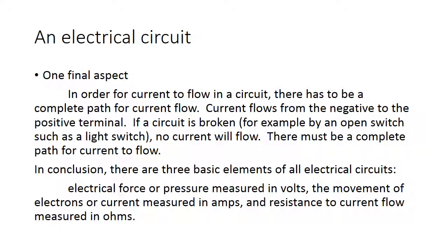Now in the next video, we'll talk about the most basic electrical circuit there is, which is the series circuit. And we'll also talk about Christmas lights. I don't know if you've had the problem or not, but if you've ever bought a string of lights that are wired in series, what happens is when one of the bulbs burns out, because the string is wired in series, it causes all of the bulbs to go out. And it can be a real pain to figure out which bulb is burned out.